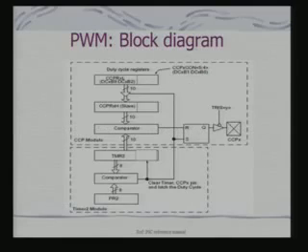So, how does it happen? Let us look at this. Now, what have you got? This is your Timer 2, and this Timer 2 can be compared with this PR2, and by that I can control the period. Using this comparator I can control basically the duty cycle. What we are talking about here is the duty cycle register.